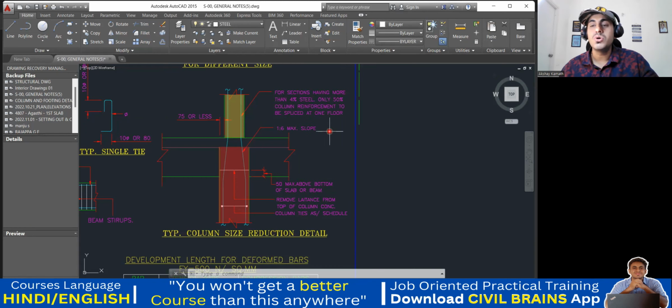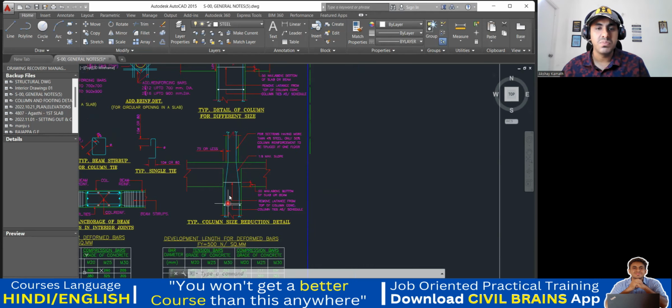That is, we should not do the lapping for more than 50% at one particular section. If there are 8 bars, only 4 bars you have to lap at one section. The remaining 4 bars, you take to the other section. Simple. So this was all about the typical column size reduction.